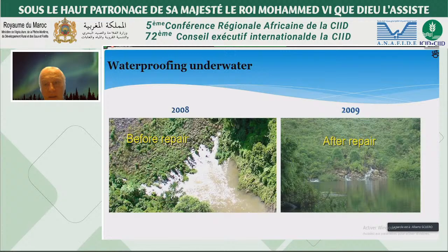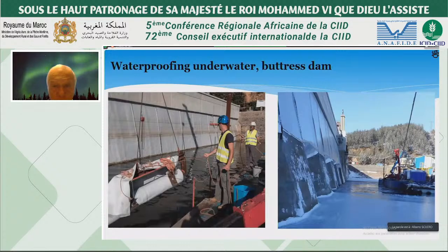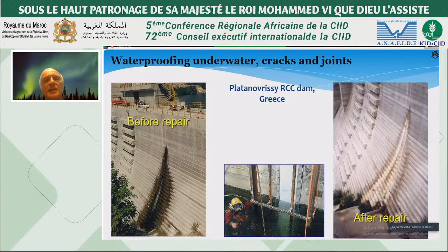A similar case is the buttress dam of Studena, a dam for water supply and irrigation in Bulgaria. All the works have been carried out underwater, even during winter conditions. We can see the divers at work, and the exposed PVC geocomposite has been used also for repair of existing dams, like, for instance, the cracks at the Platanovrisi Dam in Greece. We can see again before and after the repair.